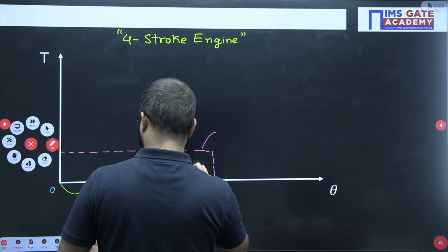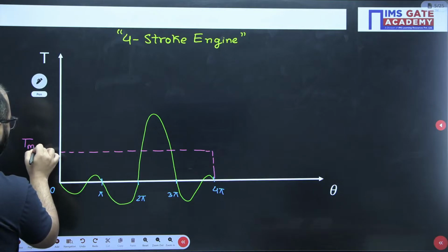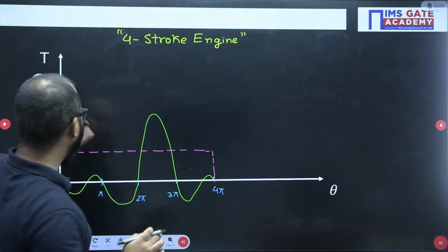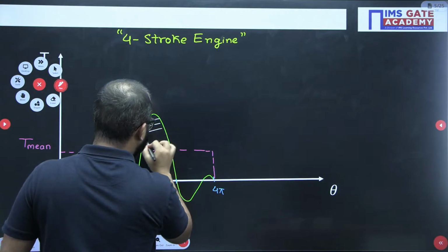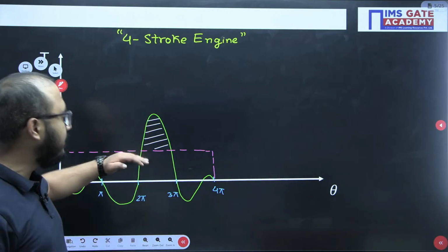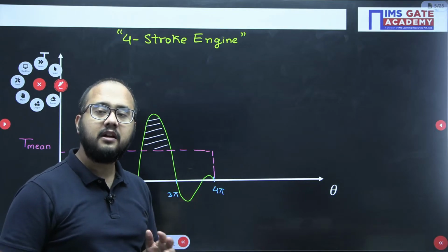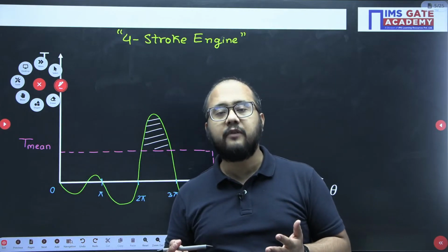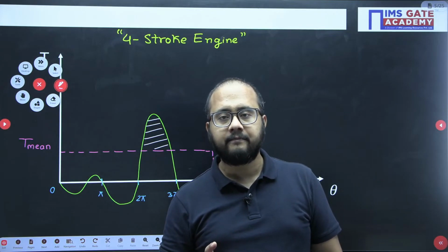Okay. Now, very important point that we need to understand here is this is the mean resisting torque which is required by the engine to just overcome the load. And I have also told you this point: whatever area we are having above this mean torque line, that is the excess energy produced by the engine. So that excess energy is going to be stored in the flywheel. See, purpose of flywheel is what? To store excess amount of energy and release it back when it is required, right?